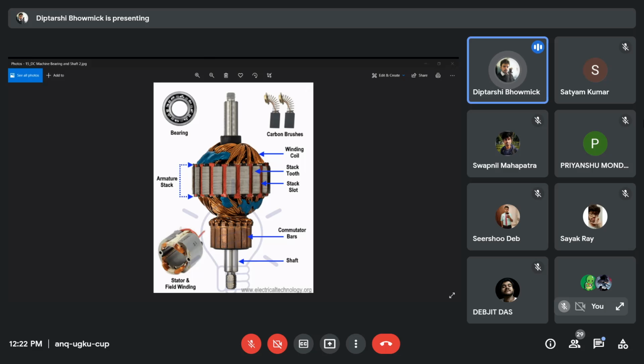And as the type of lubrication, we normally use grease for the bearing. If you go to any cycle repair shop, you can see the ball bearings mounted inside the wheel axle. That's why the wheel can move. Sometimes if you take your cycle to the repair shop, they will dismantle it, take out the bearings, clean them and put some new grease over there. So grease is basically for lubrication. Here also, in the case of ball bearings, we use grease lubrication.